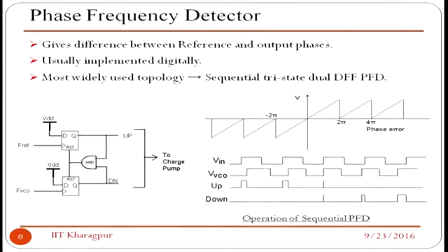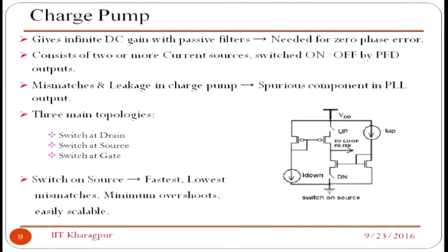This is a very classical problem, where the charge pump will be at haywire. Zero phase difference should mean no voltage, but in that case there will be uncertainty in the controlling of this VCO. So you need some sort of delay, and this is how this structure works.